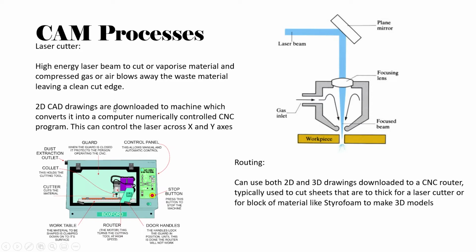So what you will have for that, you need a 2D drawing, which you can create in things like 2D Design or Fusion, and you need something called a DXF file. These machines are typically referred to as CNC, which stands for Computer Numerical Control. Because when you do that, the machine isn't actually seeing your drawing. It doesn't see it as a drawing. What it sees is loads of numbers, like coordinates, and that's basically telling it where to move.